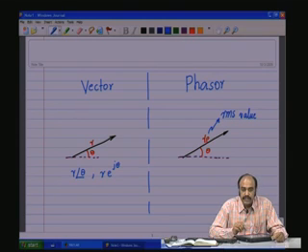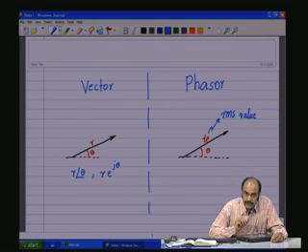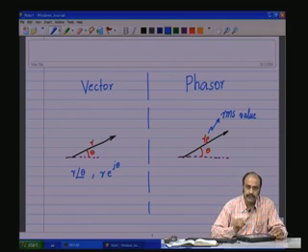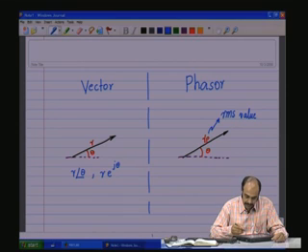That is pretty useful in sinusoidal circuit analysis because we use the RMS value in almost all cases for power, the heating content, I RMS square R, all those things. So, therefore, the phasor diagrams are extensively used in sinusoidal analysis. So, when we say phasor, remember that the amplitude is RMS in value. When you say vector, the amplitude is the exact peak value of the vector.